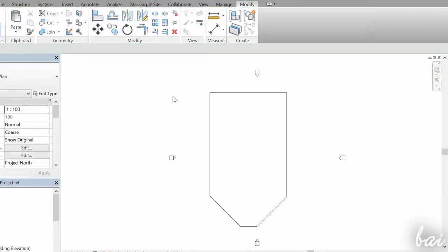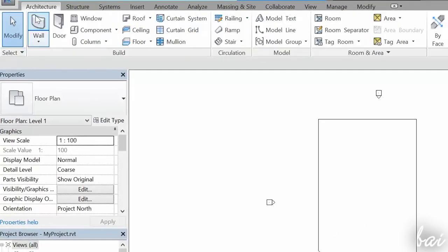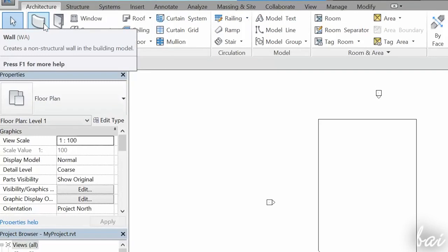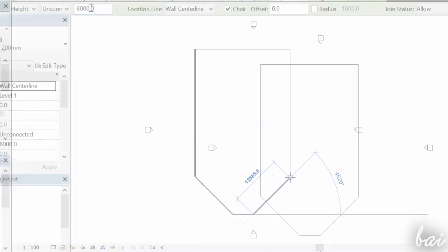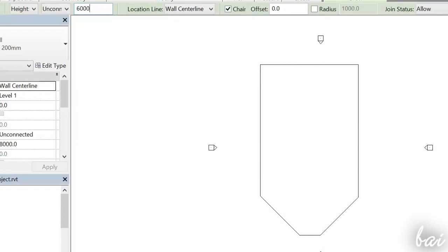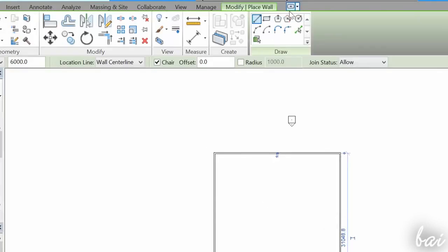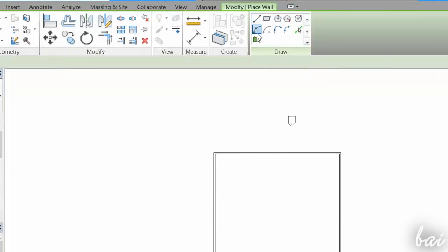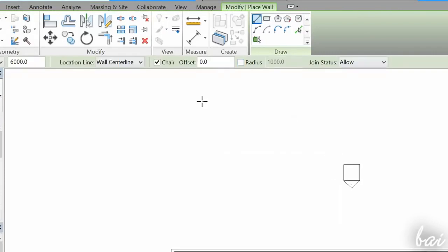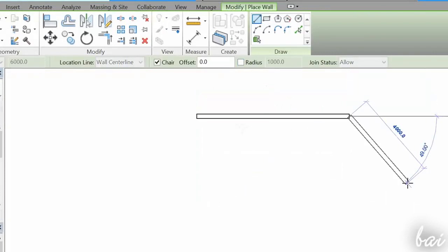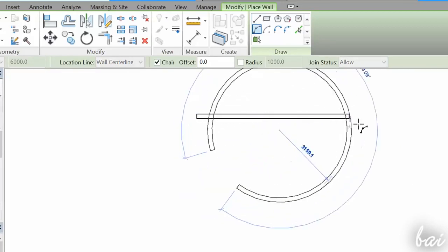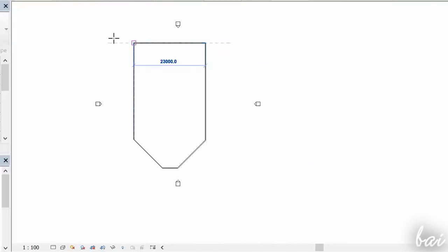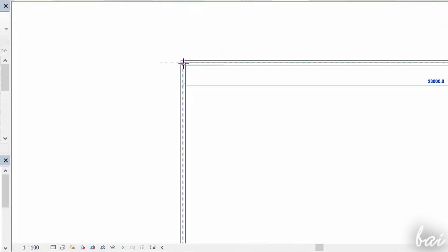After creating floors, you can go on adding walls to your house. While the floor was created by fixing its boundary, the wall is created by defining the length of its base from the top view, with its height fixed by the upper bar seen before. Under the Draw section, you can still use the drawing tools just seen in order to draw the wall base with a different shape, from the single line to the arc or a regular shape. If walls do overlap, these will automatically merge.